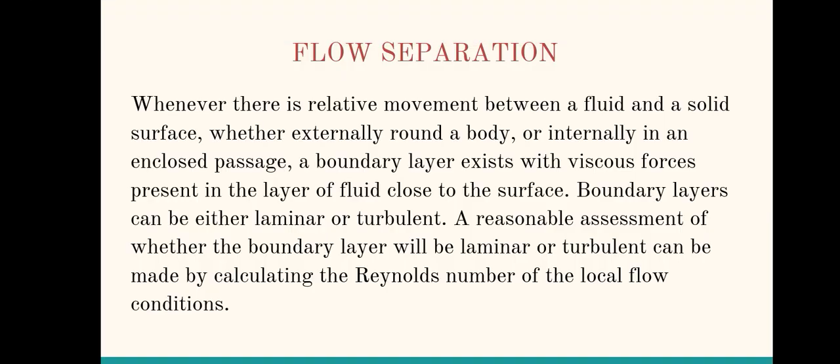First, what is flow separation? Whenever there is a relative movement between a fluid and a solid surface, whether externally around a body or internally in an enclosed passage, a boundary layer exists with viscous forces present in the layer of fluid close to the surface. Boundary layers can be either laminar or turbulent. A reasonable assessment of whether the boundary layer will be laminar or turbulent can be made by calculating the Reynolds number of the local flow conditions.